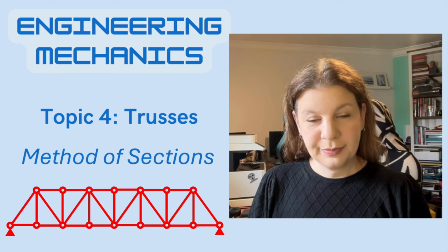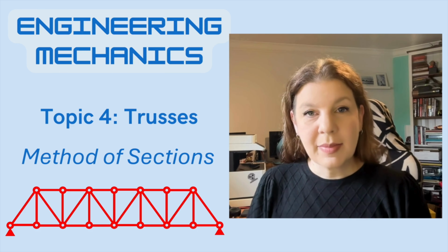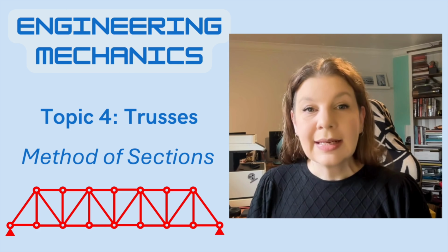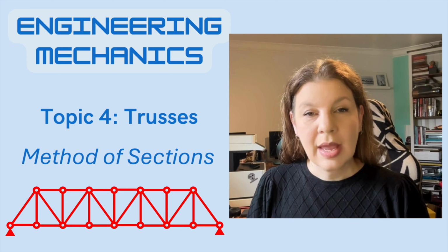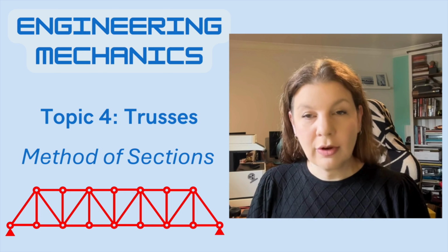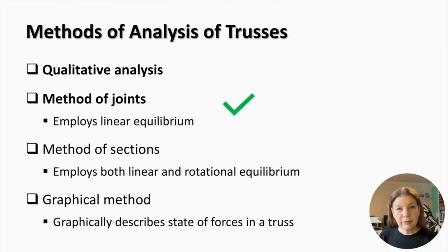Welcome to this lecture. Today we'll discuss another method for the analysis of trusses, namely the method of sections. This method is based on the solution of a non-concurrent system of forces. We already looked at the following methods that can be used to analyse simple trusses, including the qualitative method.